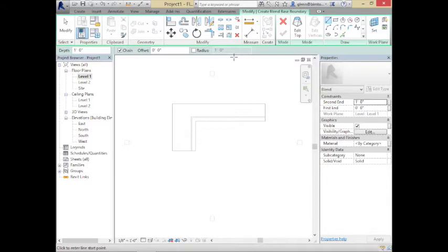You say you want to model something like this, right? And the bottom is a circle here. But imagine if this was a square top, and you wanted to model something like that. You can't use a regular extrusion because you can only make one footprint. So you use the blend. You can specify that you want the top to be a square and the bottom to be a circle, and then you extrude it along a certain distance for it to meet. It's very easy to understand once you view it.